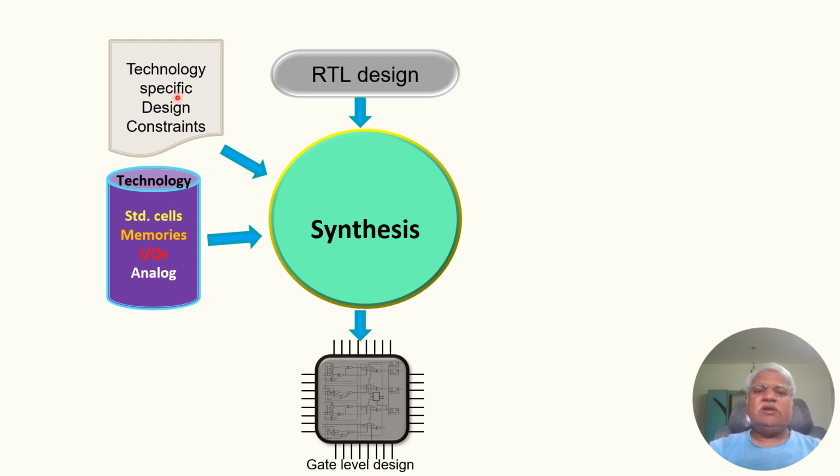Aside from that, it will also give some more information about the standard cells' multiple variants. If there are any don't use cells, they need to be mentioned, and don't touch macro blocks need to be mentioned. All that information will also be contained in the design constraints.